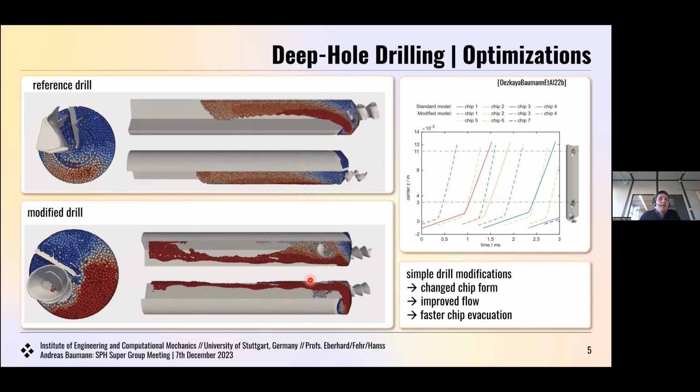And also we see furthermore that the elastic model itself isn't enough. We need also to introduce plastic formulations, as we would assume from the videos we know that once the chip is hitting the wall, we have a plastic deformation of the chip. It's not that fully elastic like it's here modeled in the simulation. And also it would be probably deforming under the fluid pressure.